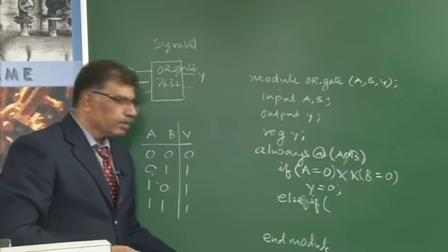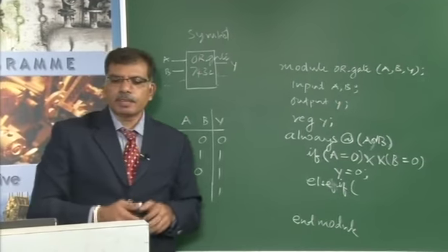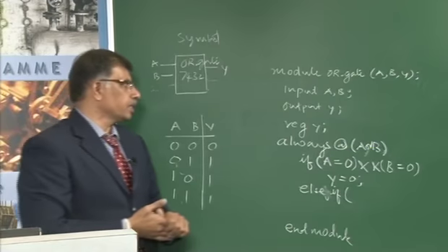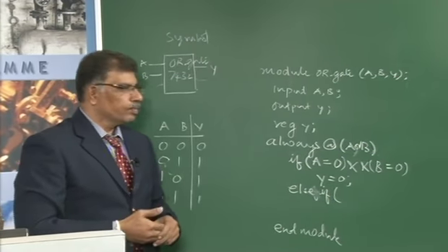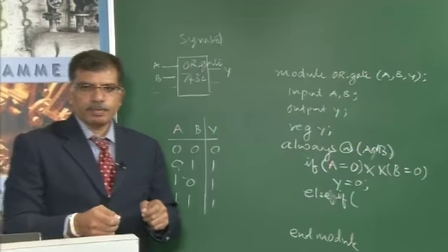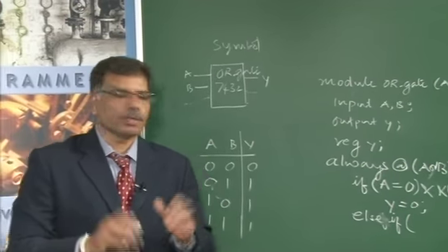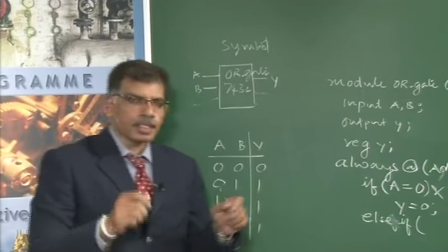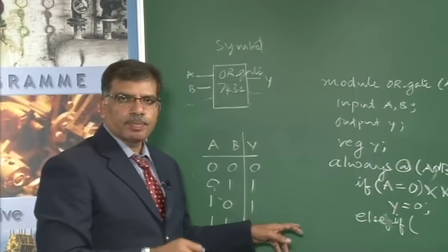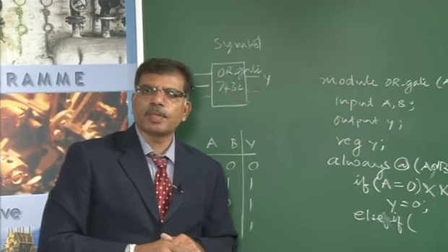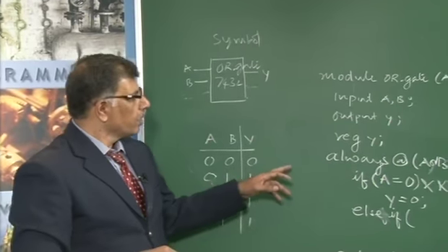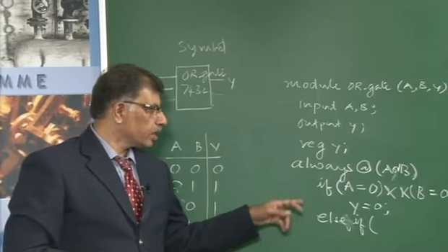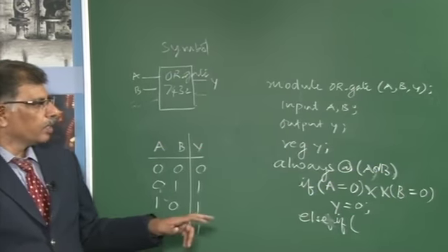So depending upon the information which is available in case of designing, you can describe different levels of representation. This is more advantageous if you don't have any information regarding logical expressions or the circuit diagram, you can directly implement it by using behavioral coding. If you have a simplified logical expression, directly you can go for data flow coding. If you have a circuit diagram, you can code in terms of a structural description.